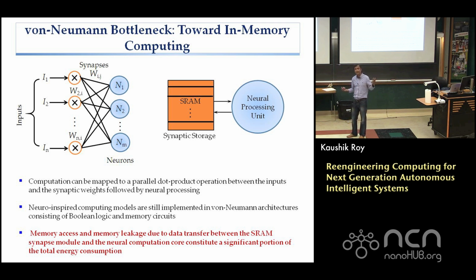In fact, in some ways, the brain does it, right? And that gives another level of efficiency. Not only having the right kind of neurons and synapses, but at the same time, if I were able to do all this computation in the SRAM cell itself, in the cache memory itself, then this traffic is going to be less, right?